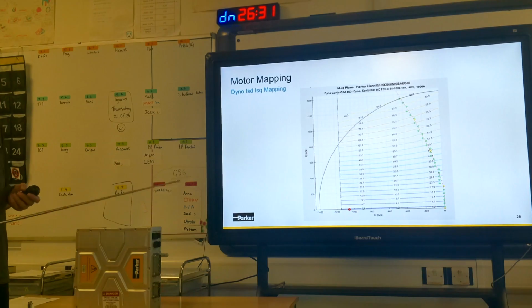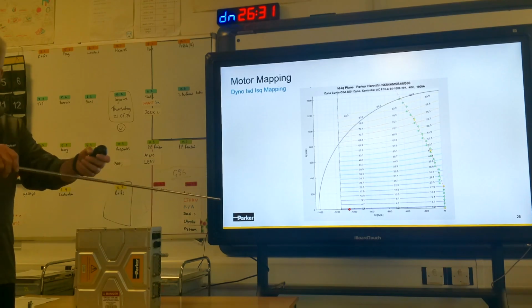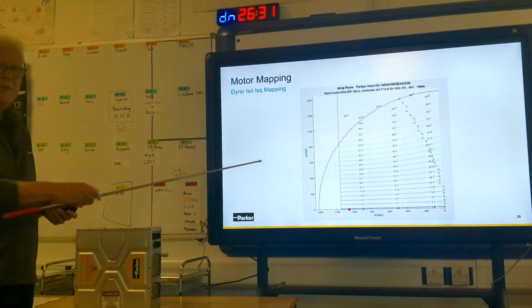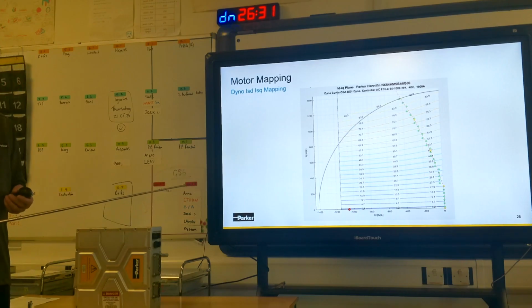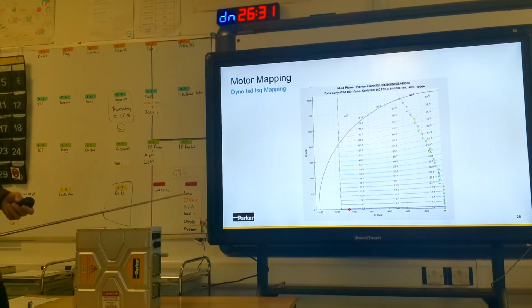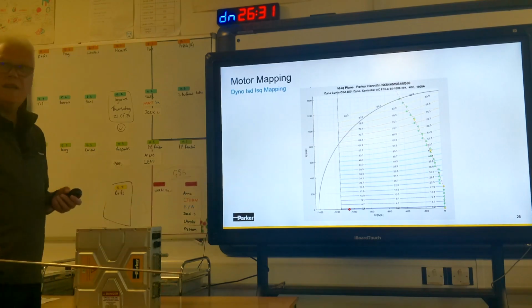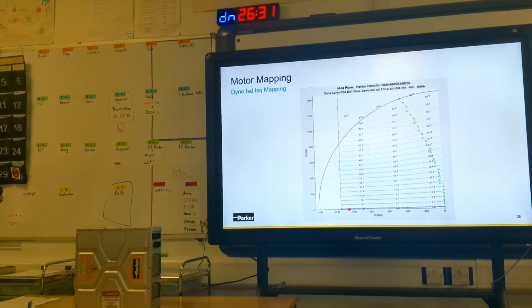This is actually a very successful control scheme for salient pole type machines. And I know some businesses who will charge you lots of money when you give them your motor to put on their inverter, to get a report that looks like that, that will tell you, for a given torque demand, what values of ID and IQ current you need to command in order to get maximum torque. Just for completeness, if you're wondering, these contour lines are contours of equal torque. But you can do it that way.